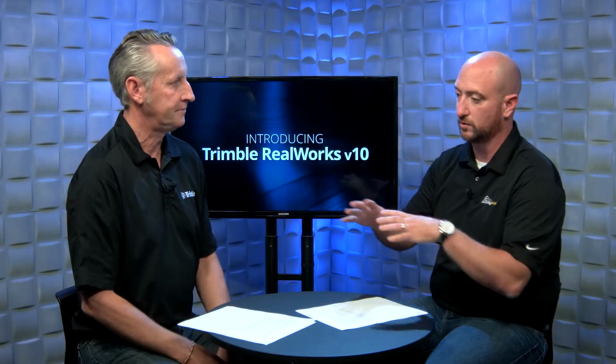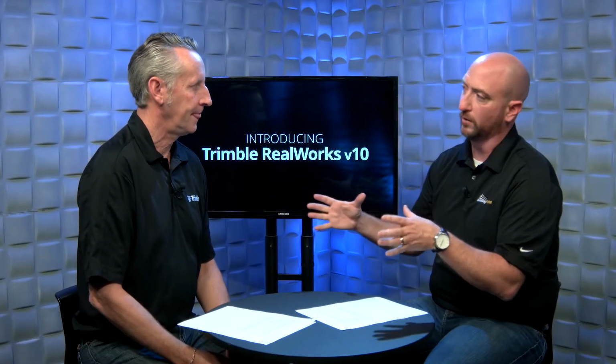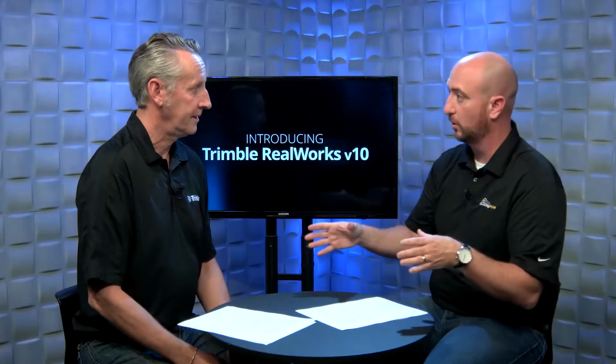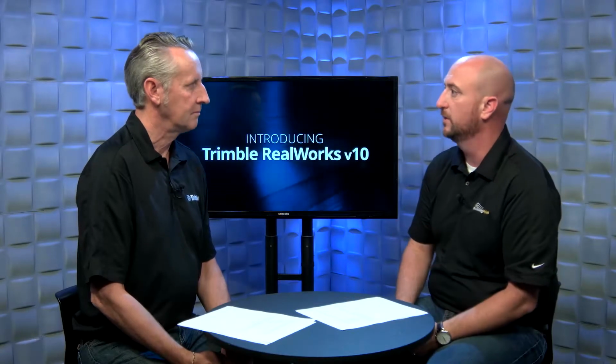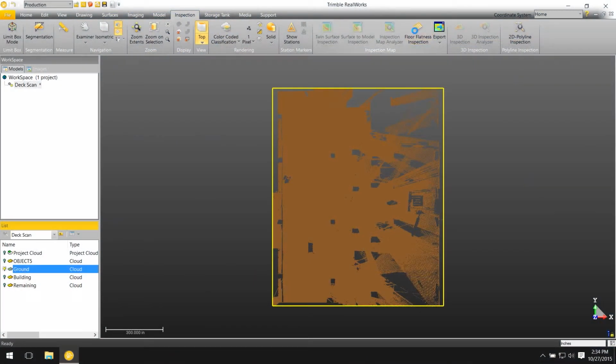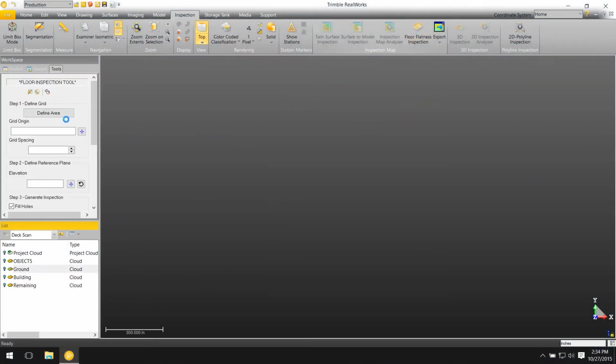Okay, so we start with the overall point cloud. With point cloud classification, we break it into smaller segments. What am I going to do if I have extracted out my ground? How can I use that data set in construction? So I would think one important step that a construction site is looking for is my floor level. So by extracting out that ground area, in this case would be the poured concrete, we can now use our automated routine for floor flatness.